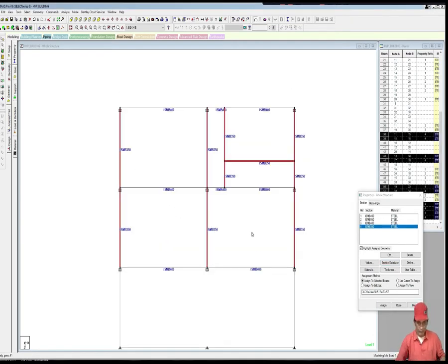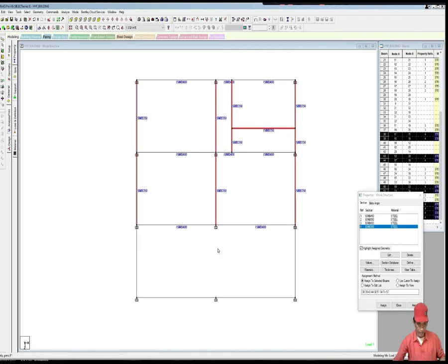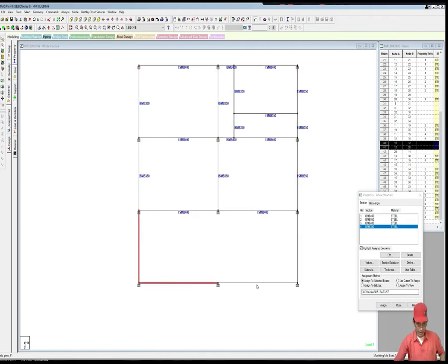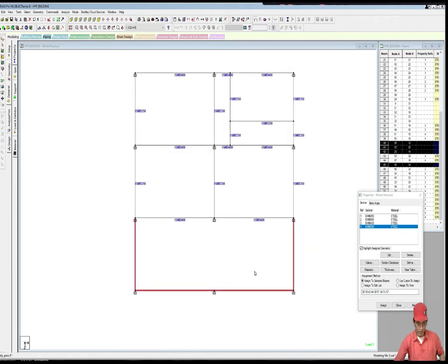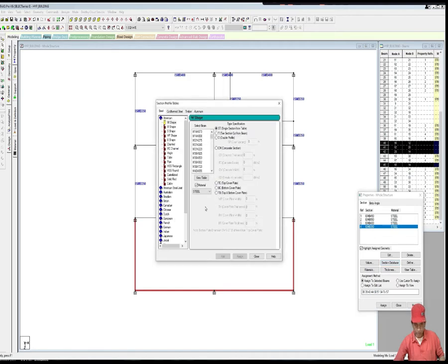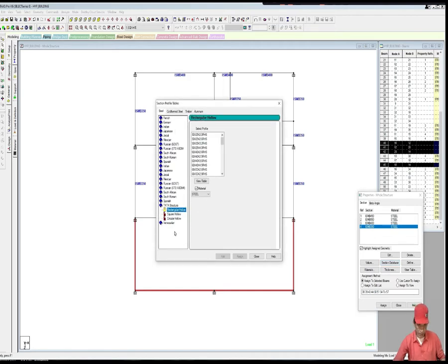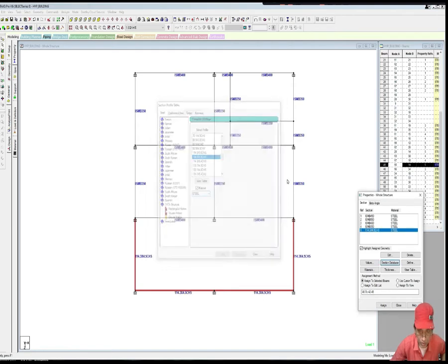Now we have the main girder property and the secondary girder properties has been assigned, and these will be our struts and ties around the column at mezzanine level. So I take tube section, pipe section here, go to Tata Structura, select circular hollow, around 100 mm nominal bore pipe of medium size should suffice. So we assign these to these sections.